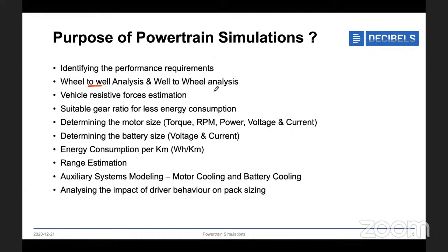And the next one is determining the motor size in terms of torque, RPM, power, voltage, and current. In real time, what will happen is that some event will give you the motor and the battery pack, you implement these two and develop the vehicle.